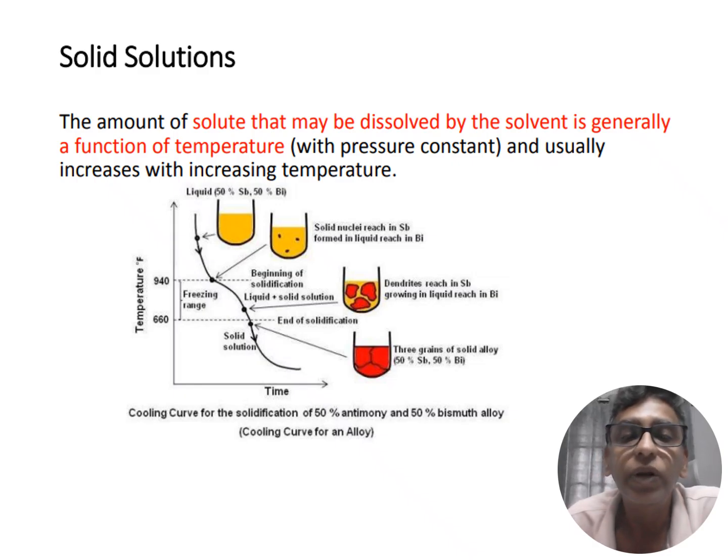So you're heating to more than 940 degrees centigrade and keeping it in a liquid state, and you are slowly cooling. The small dendrites form, and on further cooling it becomes solid; particularly at room temperature it becomes completely solid. For example, in a casting manufacturing process in the foundry industry, the different metals are melted in a furnace which is kept at a very high temperature.